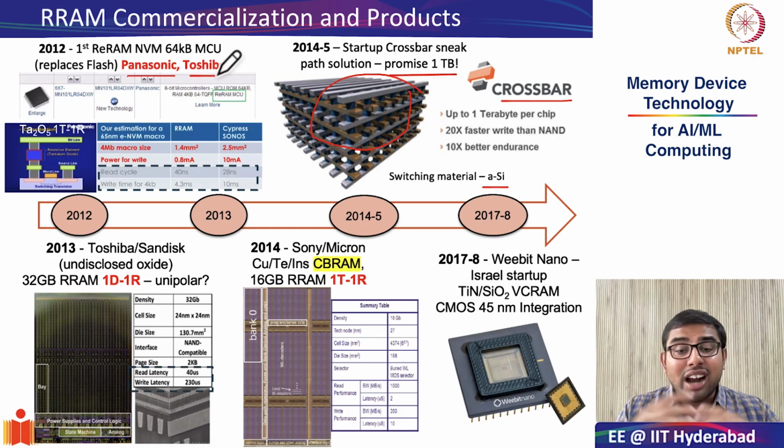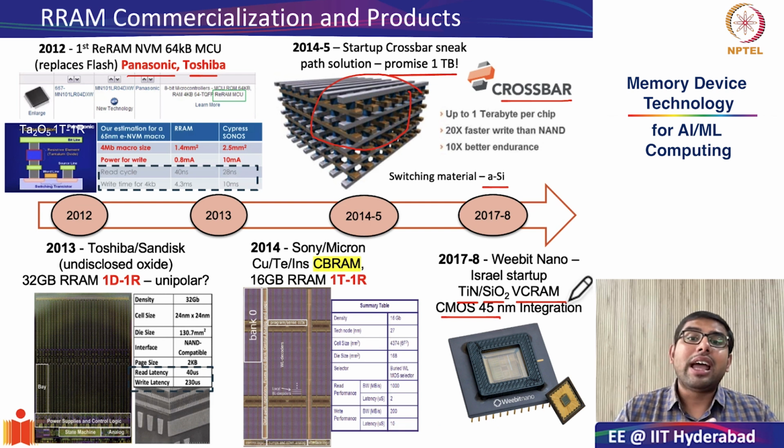Also, another startup success story is coming from Weebit Nano. This was an Israeli startup in association with the French lab CEA-Leti. They had shown CMOS integration at the 45 nanometer node for titanium nitride SiO2 based ReRAMs, and they too are showing a lot of interesting applications for embedded memories.